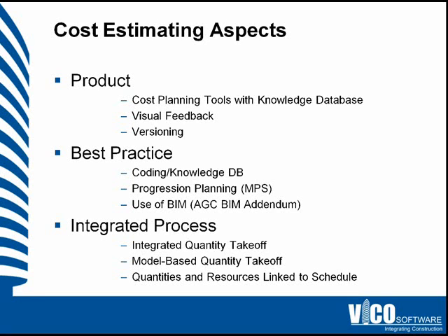As for integrated processes, there's no integrated quantity takeoff. Quantity takeoff and cost planning are done as separate activities. The quantity takeoff is done manually or maybe automated using an on-screen version of 2D takeoff. There's no model-based quantity takeoff, so the design is not integrated with the cost planning work.